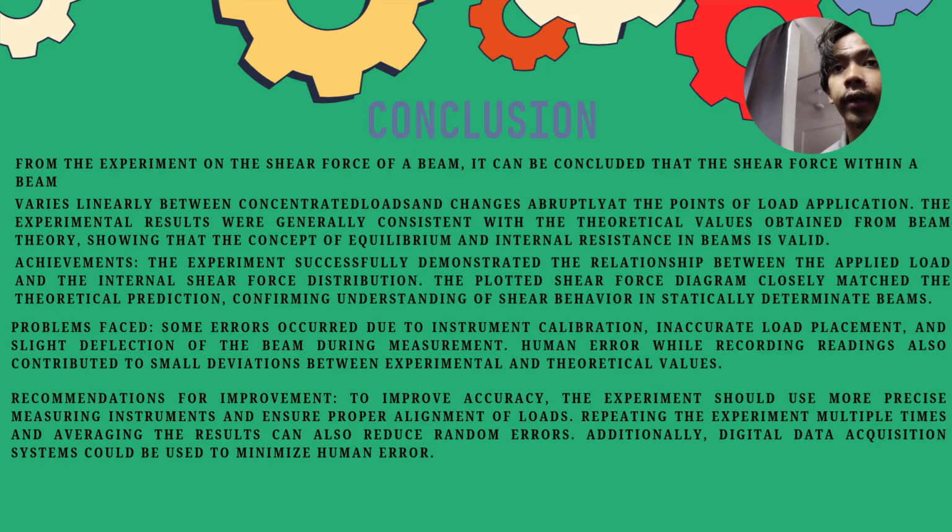The plotted shear force diagram closely matches the theoretical predictions, confirming understanding of shear behavior in statically determinate beams. The problems that we faced: some errors occurred due to instrument calibration, inaccurate load placement and slight deflection of the beam during measurement. Human error while recording readings also contributed to small deviations between experimental and theoretical values.